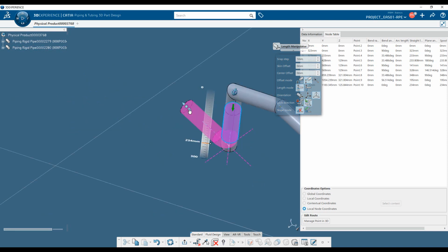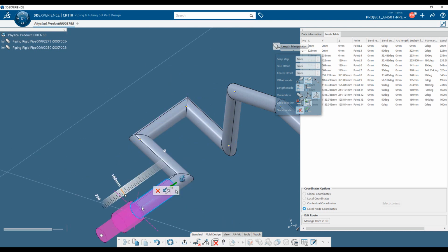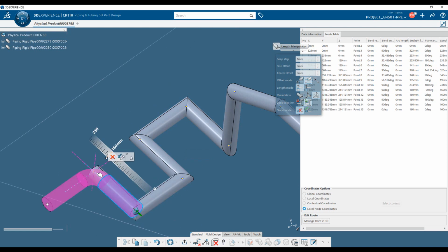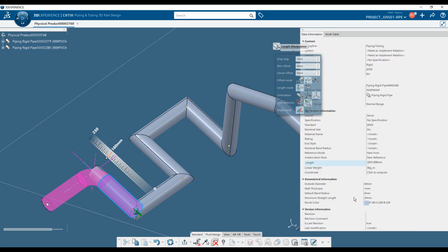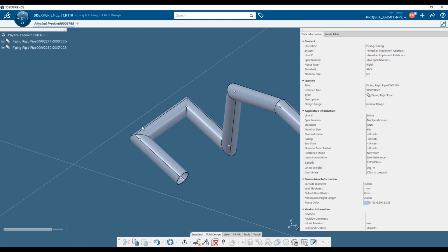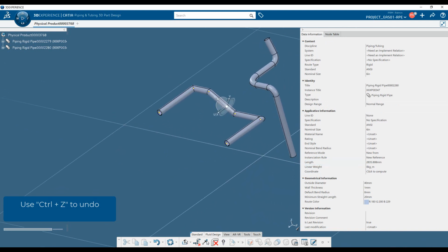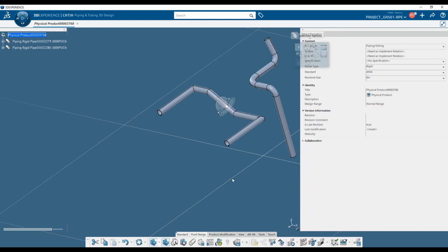At any moment also, you can press the V button and the system will create directly a point without having to drag and drop the white point. This length is hard-coded by default and is a factor of the diameter of your pipe. I think it's 4 times the diameter. So again, you can delete the point one by one if you want to go back, or press Ctrl Z to undo. And you can exit from the pipe creation when it's finished.